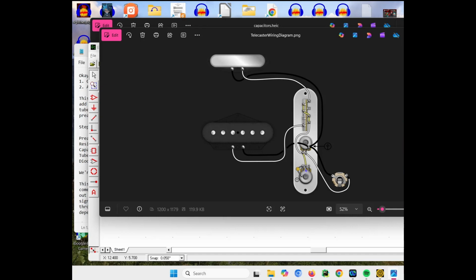Okay, and then that signal is going to go through a capacitor and then hit ground. Okay, so the thing to know about ground is that it's 0 volts, right? So once your signal goes through there, it's almost like it's getting flushed down the toilet. Once the signal goes to ground, it's not possible for it to come out of there to make it to your output jack. Okay, so the thing to note is that, again, capacitors allow treble frequencies to pass through while they give a lot of opposition and resistance to bass frequencies.